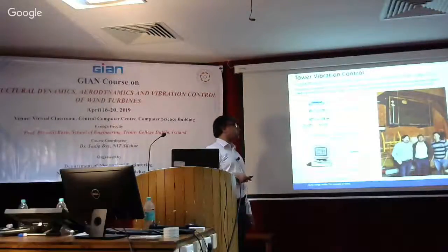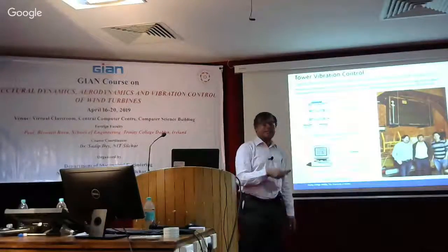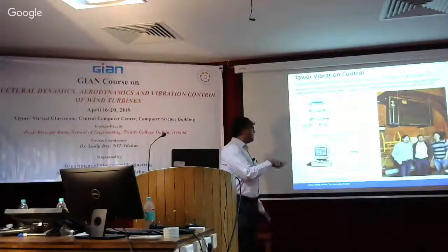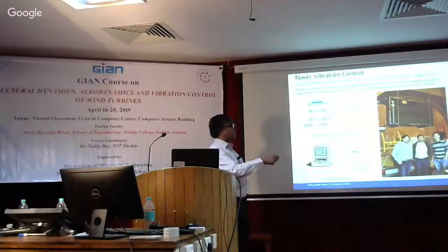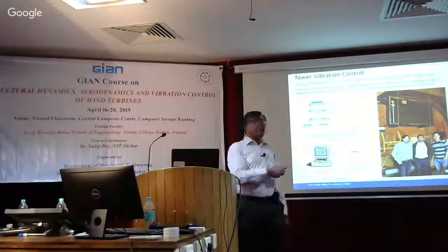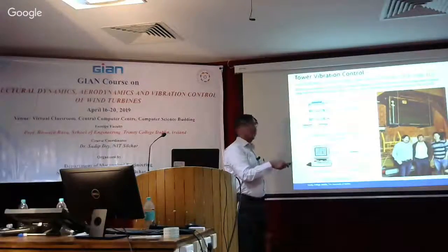Moving on to some of the experimental studies and full-scale experimental studies. This is one of the works we did where we looked at a full-scale damper. The size is exactly the same as what we put in a wind turbine blade. We simulated the wind turbine model in the computer, and there was a SCRAMNet controller, with fiber optic communication going on in real time between the physical system and the computational system. So it is as if this experiment is actually happening with the full tower integrated with that.